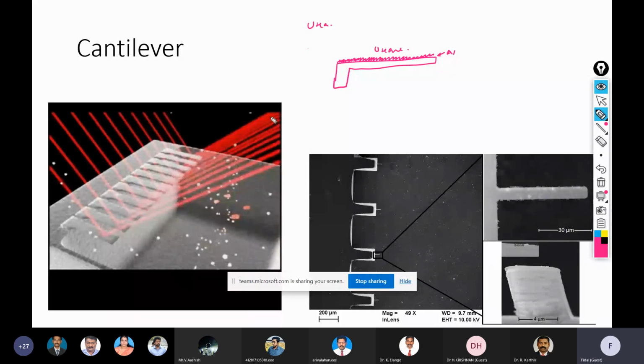Okay. Now, again, the same method. There is a laser, and the laser is continuously measuring a deflection, which is giving a frequency. Now, once the urea is put on the surface, say if you have a sample containing urea, what urease does is it converts this urea to two components: ammonia and carbon dioxide. Now, ammonia is known to be an etchant for aluminum, so it converts aluminum to aluminum hydroxide.